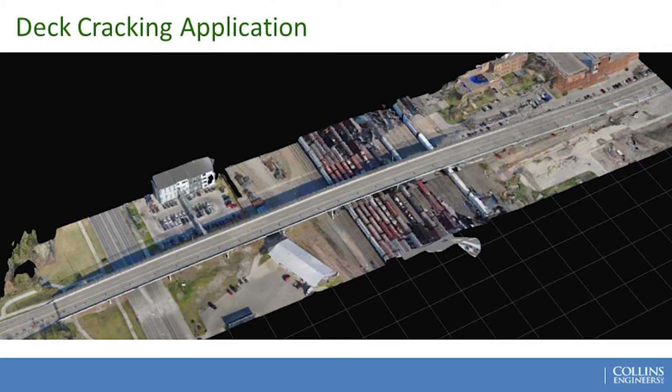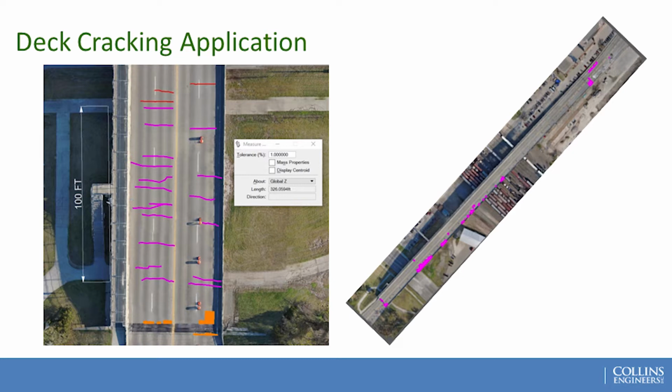If you're just getting into using drones, I think one of the easiest and best applications for it is doing deck surveys. This is a bridge we did in North Dakota where we flew the bridge, and we're able to bring it into CAD and delineate all the cracks in CAD and quantify them that way. So we have a nice record of what's there, and we get really accurate quantities, and it's much faster than